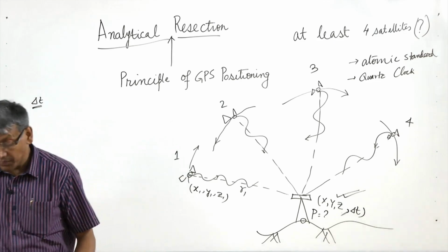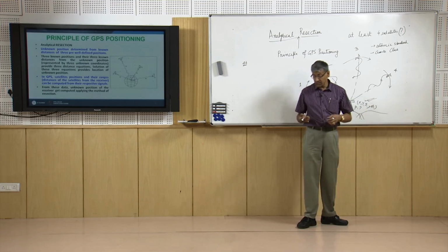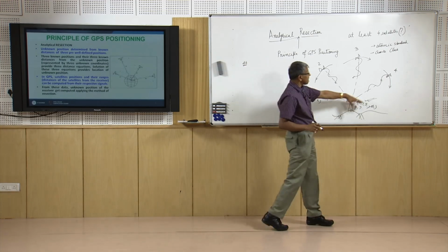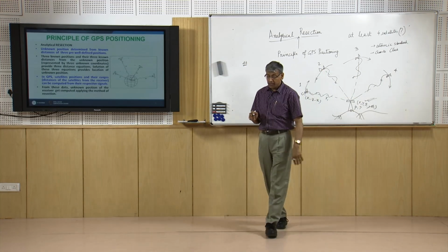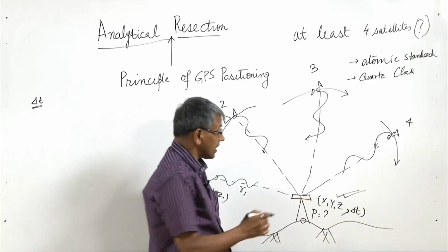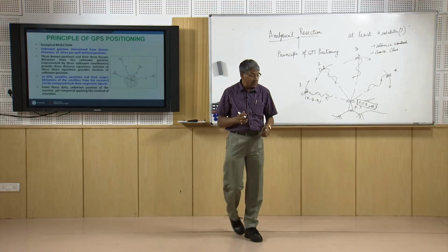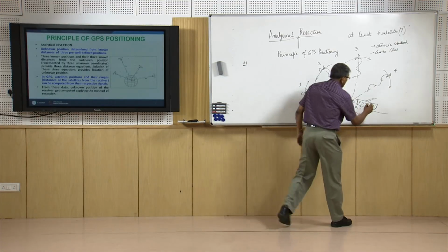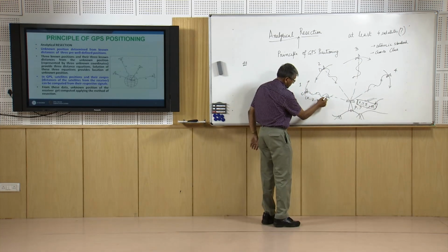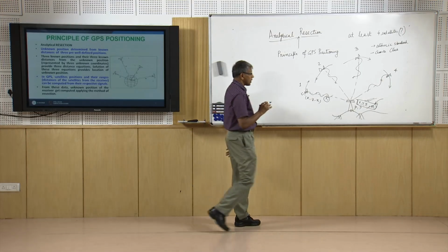So, in case of GPS it is not 3 but 4 parameters we need to measure, and so we need to have at least 4 satellites from which signal has to arrive at the receiver to determine the position. Because time is the primary parameter to be measured, as we can see in case of measurement of range, it is the measurement of time which is required.